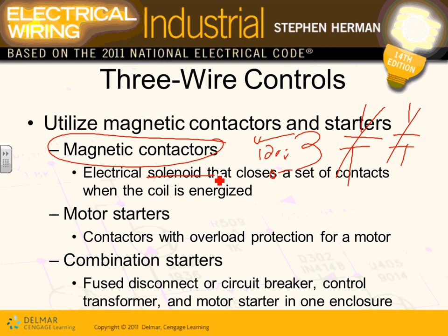Motor starters had a contactor, number one, that was on the test, and an overload, number two. So, Adam, when anybody asks you what's the difference between a motor starter and a contactor? Well, a contactor is part of the motor starter plus an overload. That's all. You're looking at it right here, gentlemen. Contactor here, overload right here. This is what you're going to be wiring when you go to the second floor.